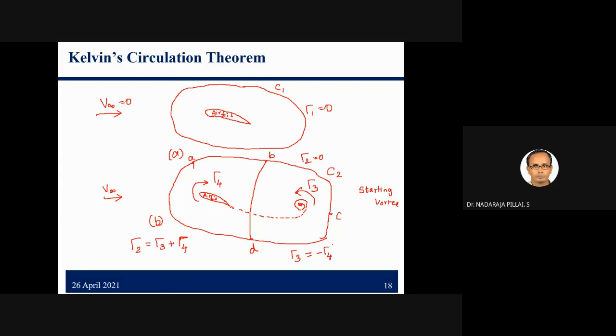So now you can imagine when there is a fluid flow, how one can calculate the lift L dash based on rho infinity, V infinity, and gamma. The gamma is produced here, that in turn creates the lift force. That is the beauty of theoretical aerodynamics, right? So I stop at this point.